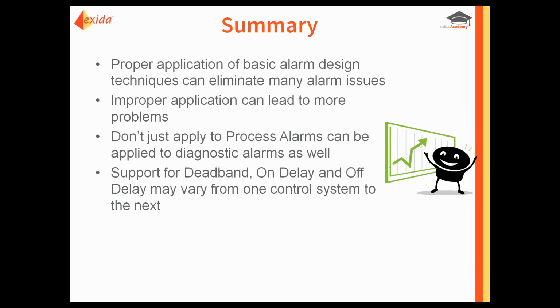We also saw that if you don't implement these techniques correctly, such as if we put in a deadband that's too large, that can create new problems. It can create stale alarms, for example, where one didn't exist before. Also want to make sure that you're thinking about applying these techniques not just to process alarms, but also to your diagnostic alarms as well. As I mentioned earlier, sometimes those can be some of the worst nuisance alarms to the operator.